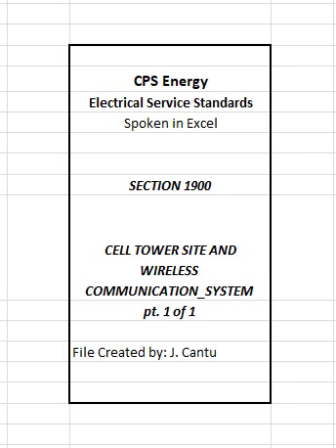1904 New service installations for wireless communication systems. Where a new service is to be installed, customer shall design service in accordance with one of the methods described in A through D below. Note: installations listed below must be pre-approved by AHJ. A. Overhead service on CPS Energy distribution pole. Service and metering equipment shall be designed to be installed on CPS Energy's distribution pole along with necessary communications equipment.